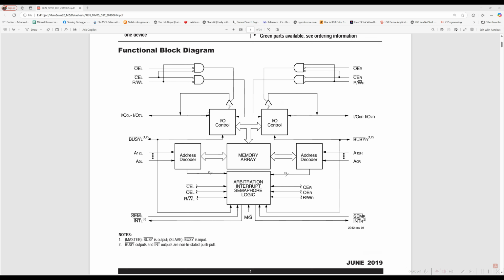The problem, I think, is that since we're enabling the chip and the output enable is low, it's sending the signal and driving against the AC 245 bidirectional bus transceiver. So they're butting heads with signals right there. One of them can be damaged, or both of them could be damaged.